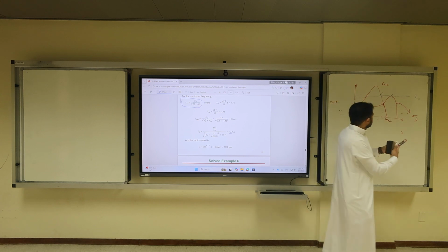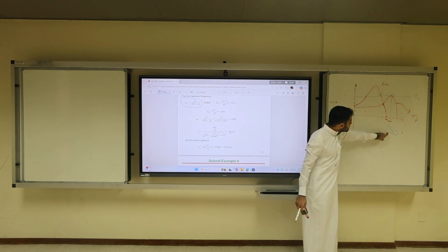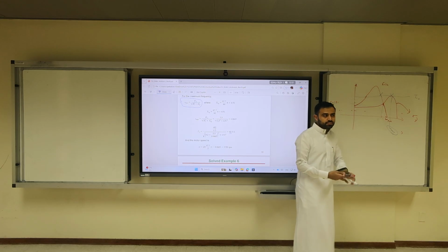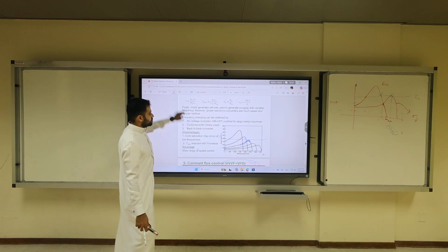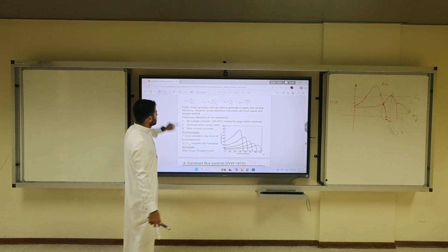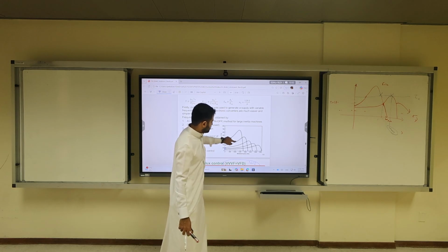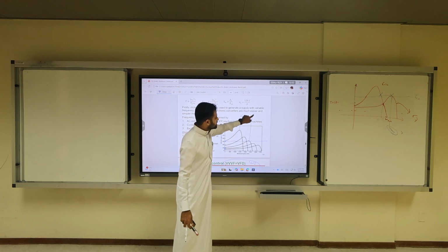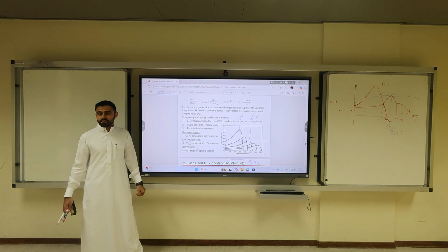So the slip here, we have omega 2 max. So I'm increasing my slip for the 67 Hertz, while the original slip for the 60 Hertz is lower. Looking at this curve, this is the 180. This one is the 60. This one is the 67. Clear now? Yes. Doctor, isn't it overall a negative to operate at 67 because you're operating at maximum